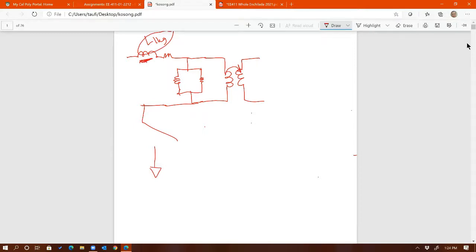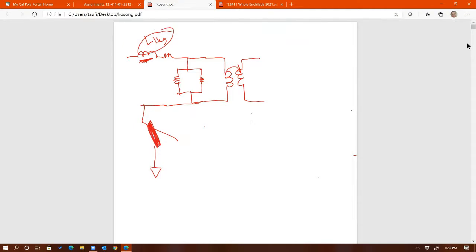So imagine if this switch is conducting, you are storing energy into this inductor, right? And what happens when the switch is turned off? The winding is coupled to the next winding, so when the switch turns off, its energy is transferred into the next winding. But the energy stored by this leakage inductance has to go someplace, right?